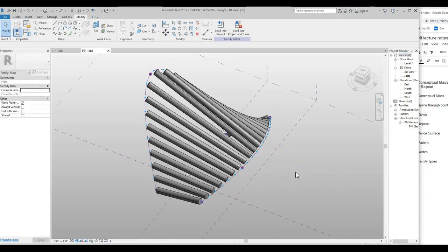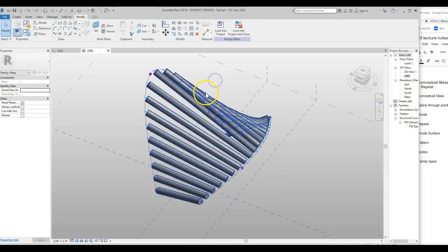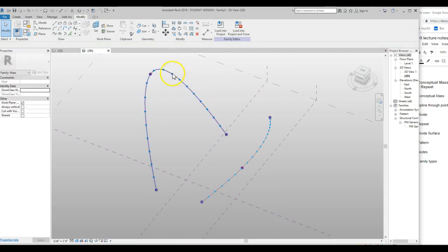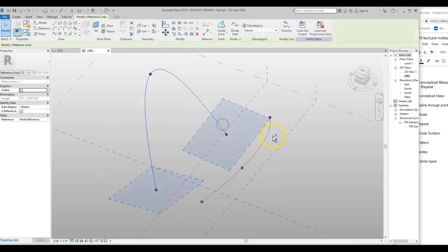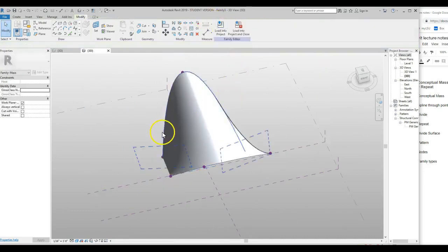So now there's something else we're going to do. We are going to look at a different way of playing with this. I am going to grab all these and go HH and just hide that. I'm actually going to delete them, all of them. I'm going to delete the divided surface and just go back to when we just had the two splines, right? So you notice because I didn't delete the line, I deleted the skin of the divided surface on the line. I'm going to grab these two things right here, and I hit create surface.